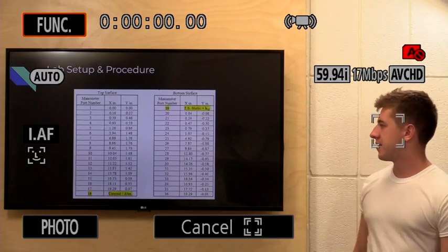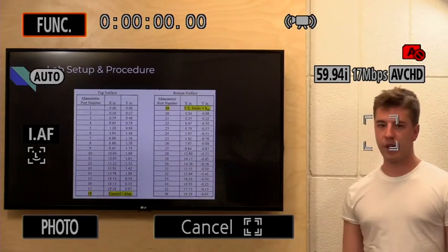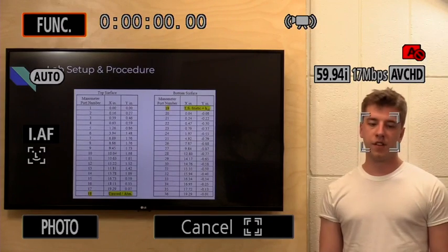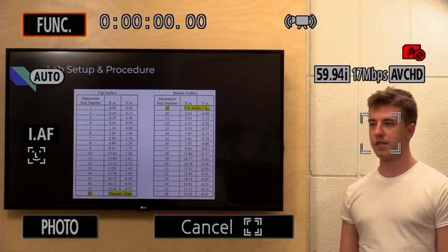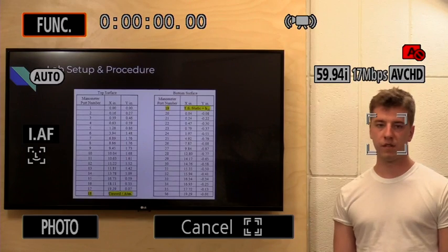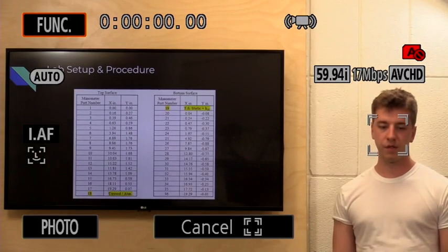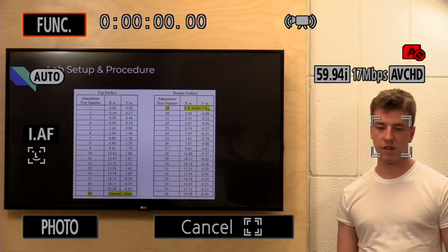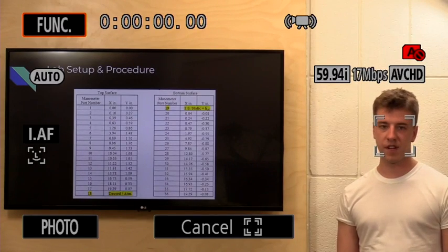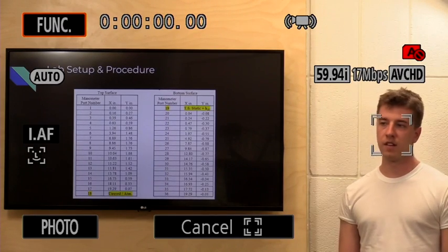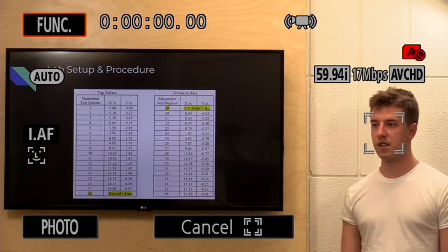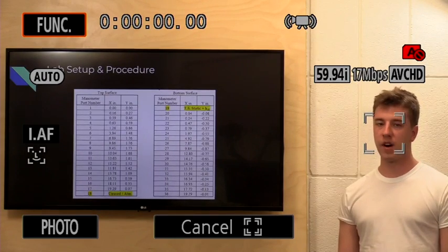So this is a chart of the channels used in the manometer bank, where channels 1 through 17 were used to measure the upper surface of the airfoil. Channel 18 was used to measure the atmospheric pressure. Channel 19 was used to measure the static pressure in the wind tunnel, and channels 23 through 36 would measure the static pressure at the bottom of the airfoil.